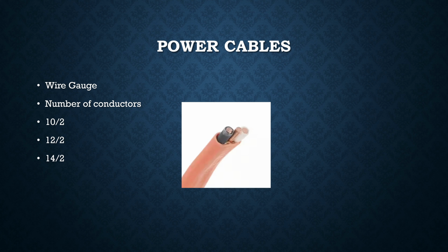You're going to connect that wire to all metal things. It's designed to be a safety mechanism. So all metal things are connected to each other in the system in case of a ground fault. And the other two wires, you can think of it like the outgoing and the incoming, right? So the black wire would be the hot wire, and that's theoretically the energized, the voltage applied side of the circuit, and the white is the neutral wire, which is where the electricity can return back to the panel.